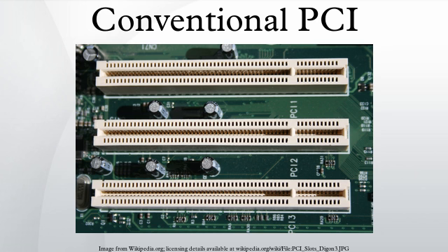The card connectors used for each type include: Type I and II use a 100-pin stacking connector, while Type III uses a 124-pin edge connector. That is, the connector for Types I and II differs from that for Type III, where the connector is on the edge of a card, like with a SODIMM. The additional 24 pins provide the extra signals required to route I/O back through the system connector.